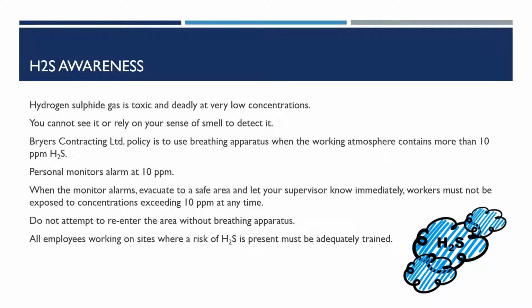H2S awareness. Hydrogen sulfide gas is toxic and deadly at very low concentrations. You cannot see it or rely on your sense of smell to detect it. Bryers contracting policy is to use breathing apparatus when the working atmosphere contains more than 10 ppm of H2S. Personal monitors alarm at 10 ppm. When the monitor alarms, evacuate to a safe area and let your supervisor know immediately. Workers must not be exposed to concentrations exceeding 10 ppm at any time. Do not attempt to re-enter the area without breathing apparatus. All employees working on sites where risk of H2S is present must be adequately trained.